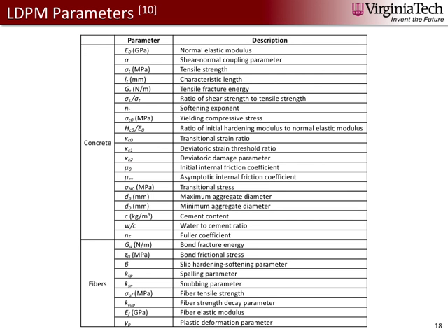A number of LDPM parameters define the behavior of a specific type of concrete. I've broken these into 2 groups. The first one describes the behavior of a specific type of concrete, and the second grouping, if fiber reinforcement is present, defines their effect on the behavior of the member during loading.